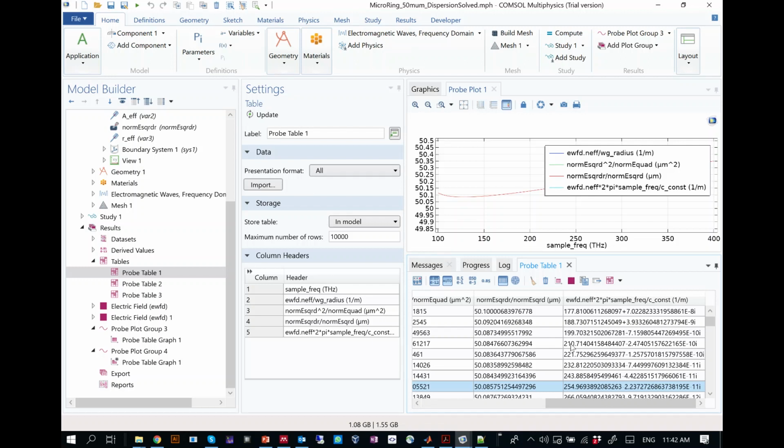What this means is COMSOL doesn't know that this is a resonator, so it calculates a bent waveguide at a certain frequency. This frequency will in general not be resonant, so you get a fractional mode number. It is basically how often this specific wavelength fits into the resonator. This being fractional means that the frequency is non-resonant. But that is no problem for calculation of the dispersion. You can still calculate the dispersion.